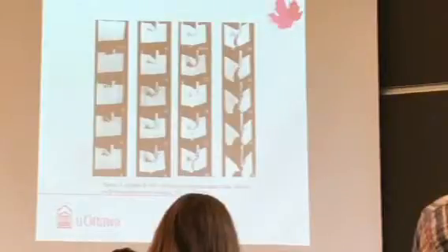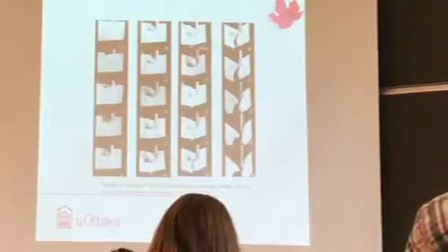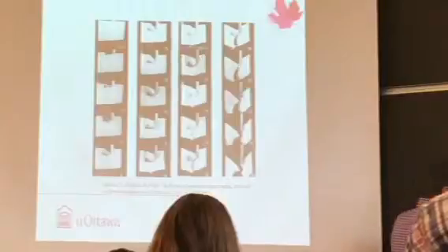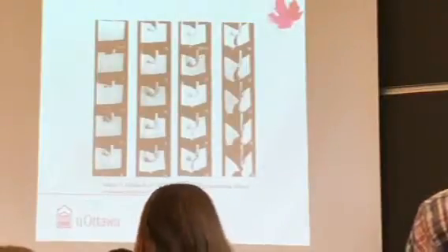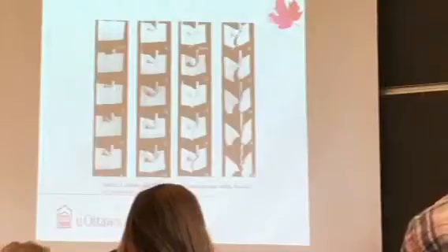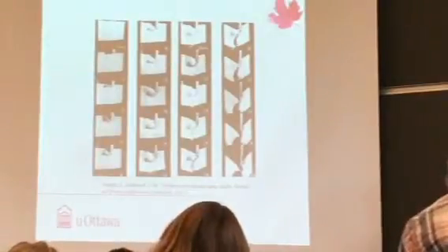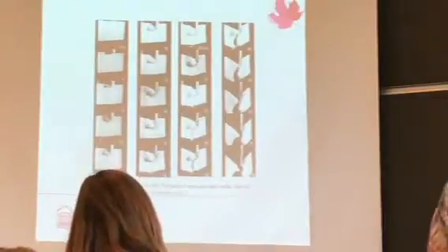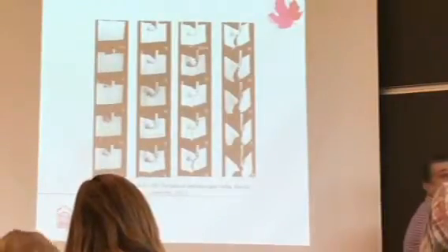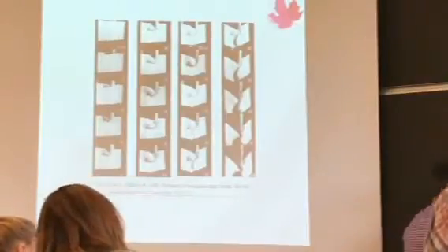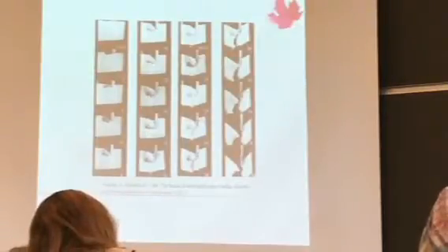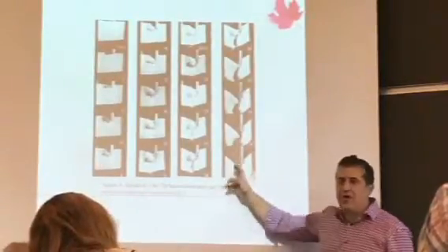So this is a typical failure, and it follows basically what we've known for very long, which is the path of least resistance. Why? Because timber is essentially pipes that are going in this direction, and to cut through the pipes requires much more energy than it does to go through a few of those pipes and then run along them, where the bonds are very, very weak, and then go back and forth, right? So this is the path of least resistance. As you can see here, it doesn't really follow the path of least resistance. It's almost like a karate chop.